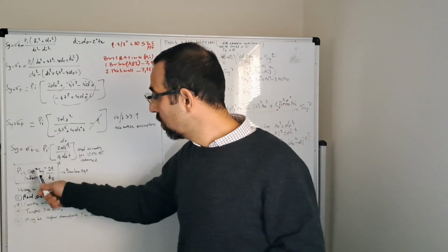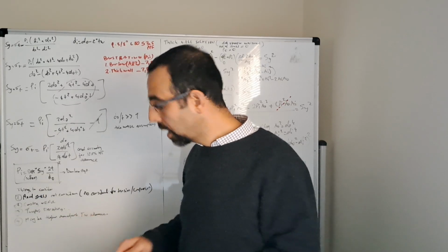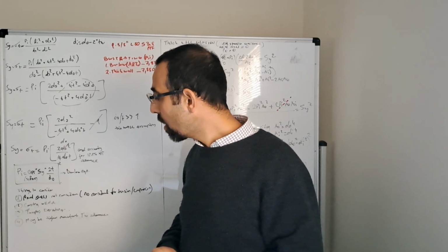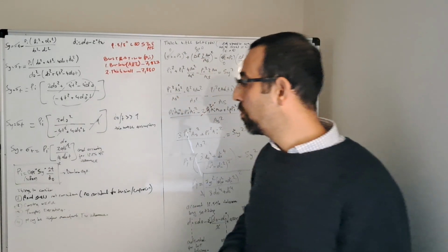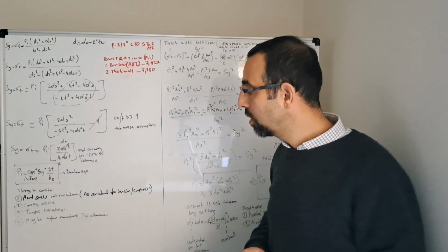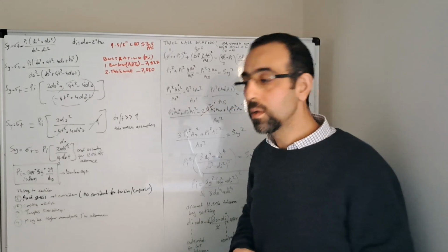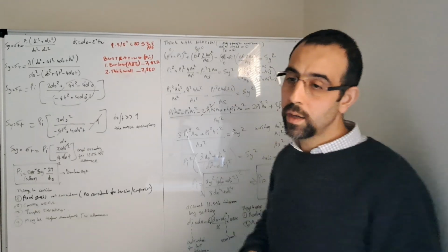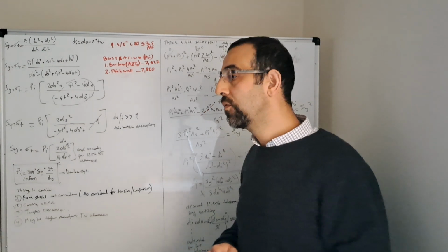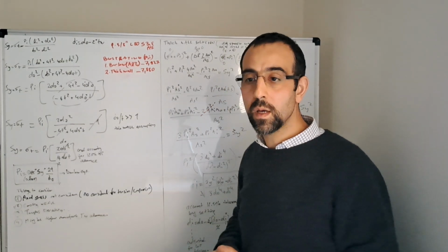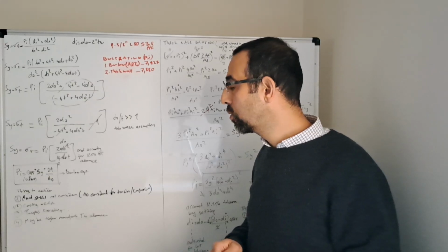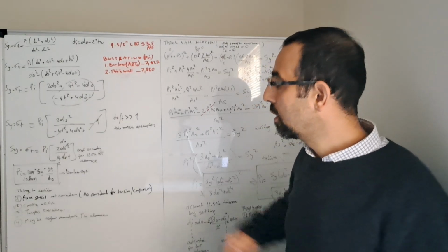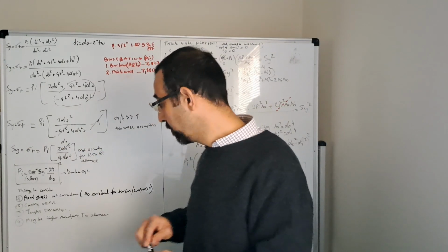And also we need to think about the temperature rating. The yield strength is also affected by the temperature, and I think the best point of contact is the vendor, depending on the grade or the specialty of the pipe, either it's a chrome or a different grade of the pipe, H2S resistant pipe. You could get the temperature derating properties of the yield strength, and then that will impact the burst rating.